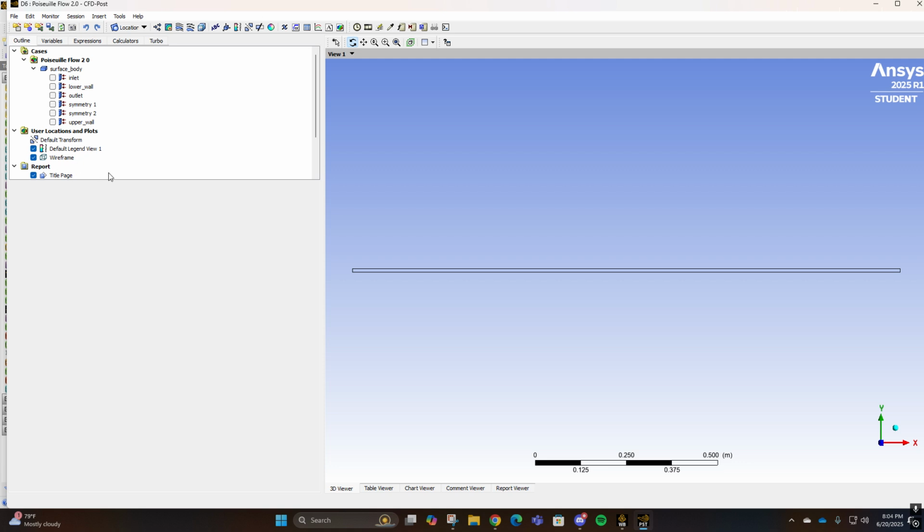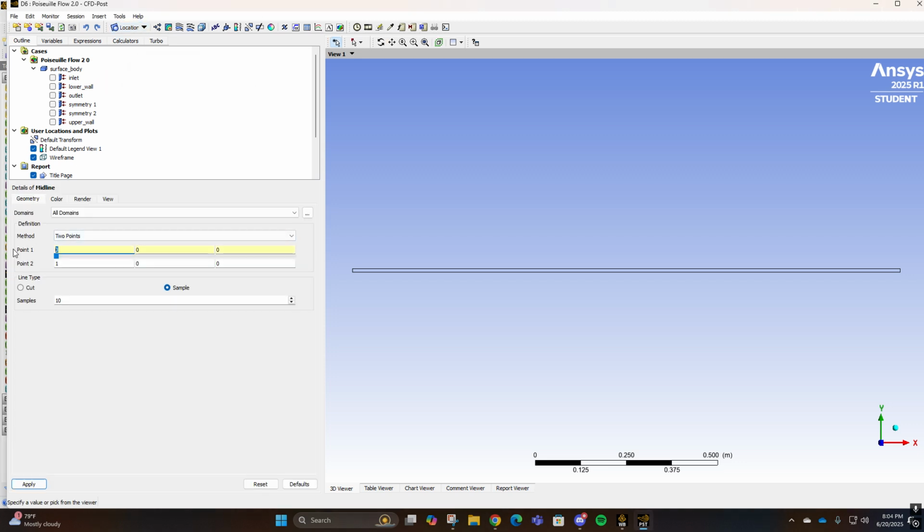So the first thing we're going to do is add our midlines and end lines so we can show the velocity profiles at those, and the maximum velocity and maximum height. So first we're going to do midline, and that's going to create here. It's about 1500, so we're going to divide by 2, make that 0.750. This is in meters, this tab, but we're just going to keep it like that. So 0.750, which is meters, 750 millimeters, and keep that sample.